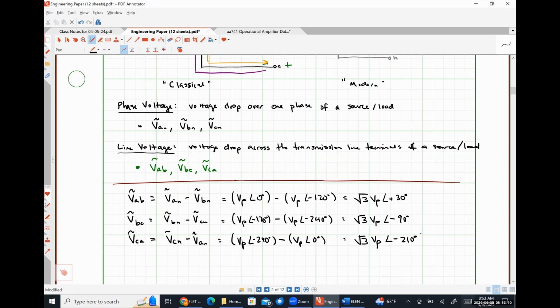So if we start monkeying around with the polarities of our voltages, all of those fundamental relationships about things leading and lagging by exactly 120 degrees are going to fall apart. So this actually is going to wind up making our life much easier because everything will always be exactly 120 degrees out of phase. Doesn't matter if we're looking at line voltages or phase voltages.